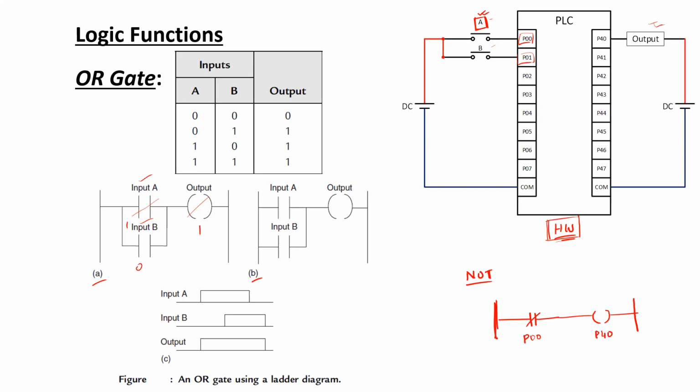If the diagram is drawn in this pattern, then it would be sufficient, because normally the contact is kept closed, so your output is getting a high signal, but whenever this switch is pressed, this particular port is getting some high signal, and it will have a transition from its initial state. So the contact that was represented to be normally closed initially would be open then, and the path for the output coil will also be open, and there will be a transition in the output as well.